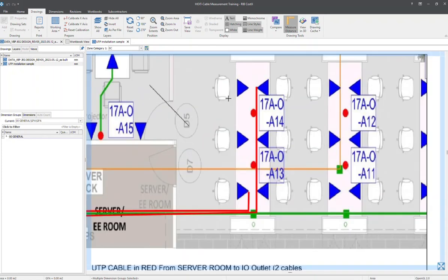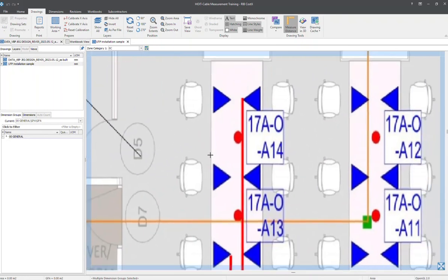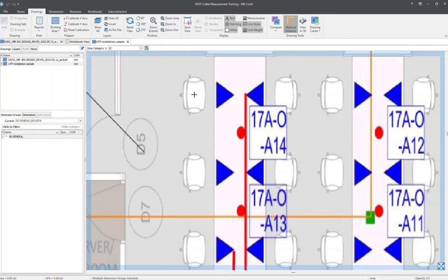In this case, the best reference is to see from one workstation to another workstation. For example, I take this one workstation and drag it to another workstation, and you can see that it actually shows 0.022 meters. It's about 22 mm, right? So in this case, for sure, it's not logical. So it means that we need to calibrate it to use the right calibration figure.